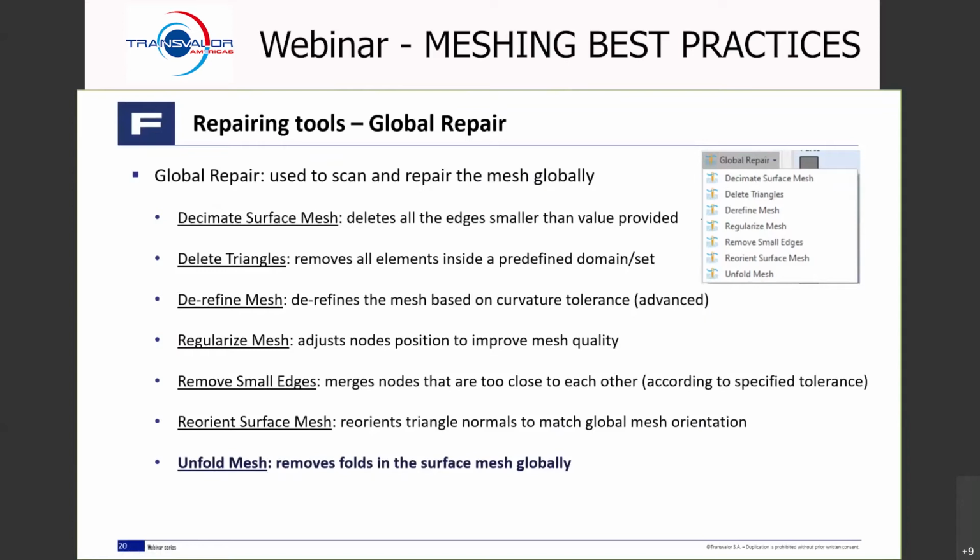The issue with this is that sometimes we have too many faults and the tool can get overwhelmed by all those faults. Or sometimes the faults are removed drastically, and you can even see some holes in the model after removing the faults. So after running this tool, even if the faults are removed, you should double check your geometry to make sure it works properly. It's still a tool that is being improved every version, so be a little careful when you use it.